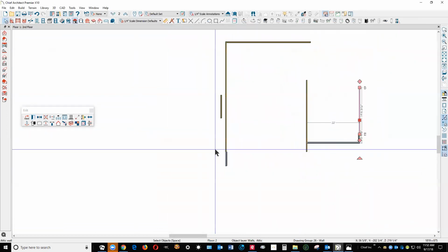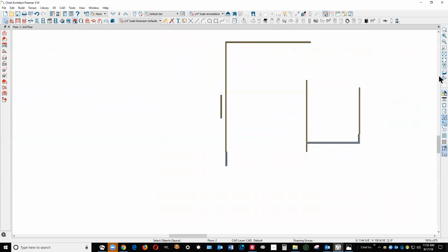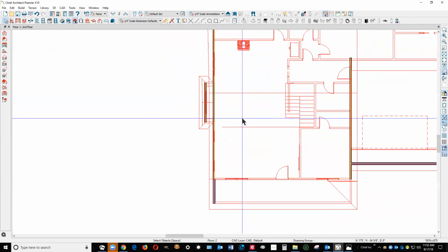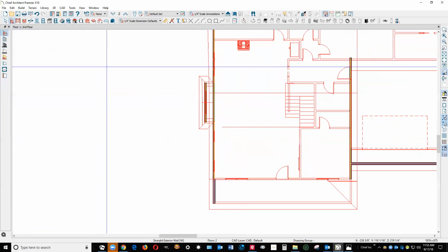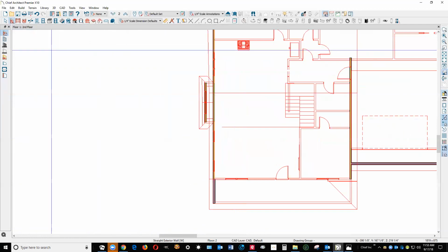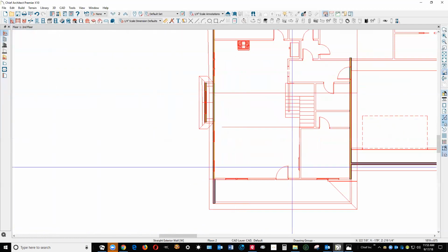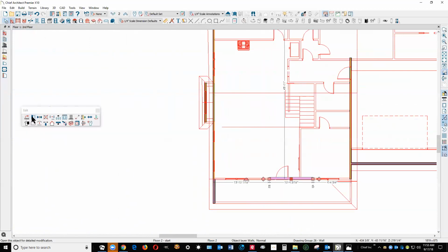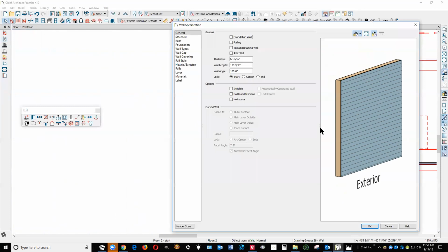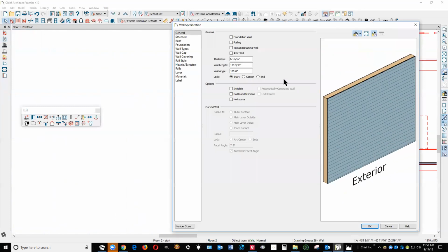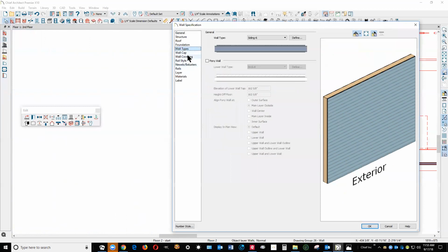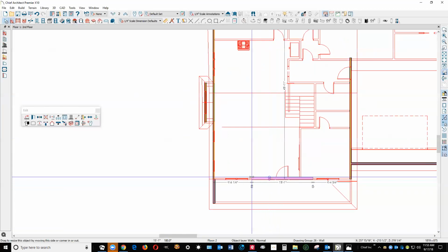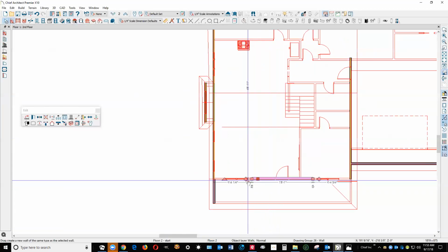So I'm going to ignore those walls, turn on the reference display, and just draw me up a little room based on the photograph. We'll go to the exterior wall tool, see what you have. You have it set to CMU. Oh, not CMU. That's a really fat wall. Siding 6. Okay, siding 6, fine. Now I'm just going to draw a little room up here on the second floor.